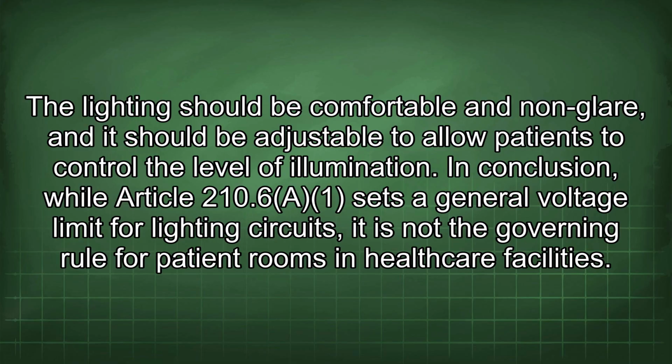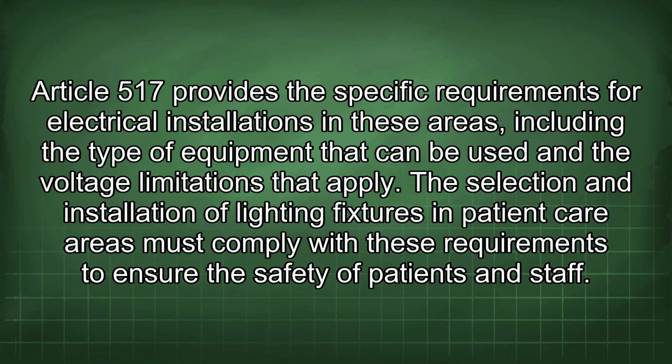illumination. In conclusion, while Article 210.6(A) sets a general voltage limit for lighting circuits, it is not the governing rule for patient rooms in healthcare facilities. Article 517 provides the specific requirements for electrical installations in these areas, including the type of equipment that can be used and the voltage limitations that apply. The selection and installation of lighting fixtures in patient care areas must comply with these requirements to ensure the safety